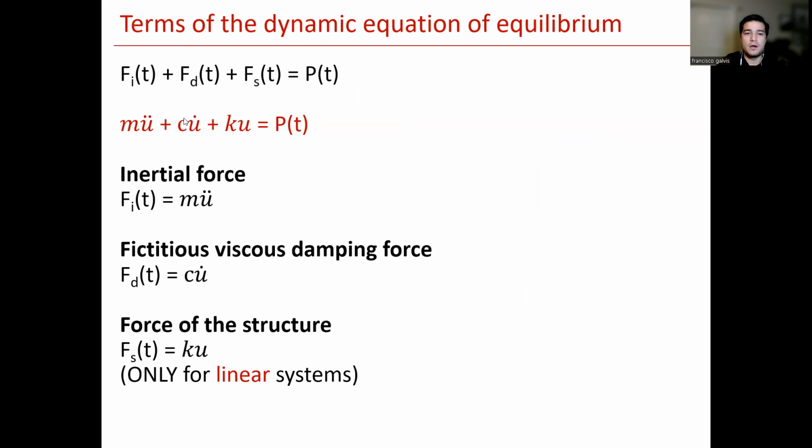So we got a damping constant multiplied by the velocity, and then the internal force of the structure, the deformation in the structural members if we are linear elastic, is just the stiffness multiplied by the displacement. And this is really important to highlight: it is linear elastic. And that equals the external force, right?